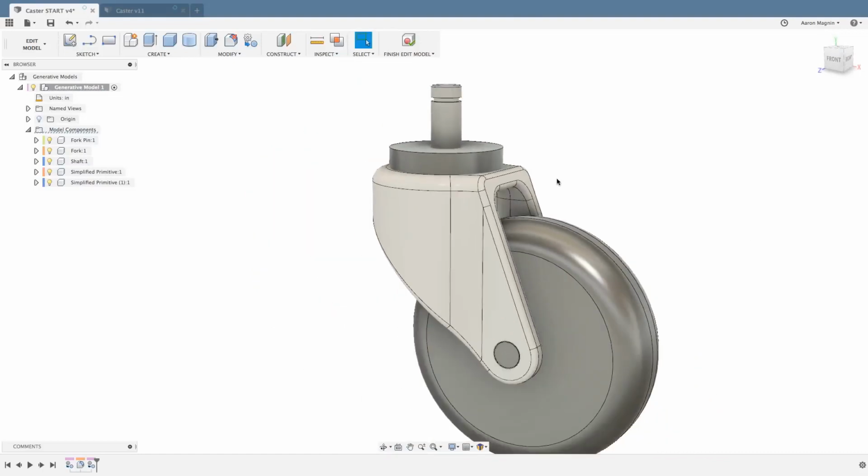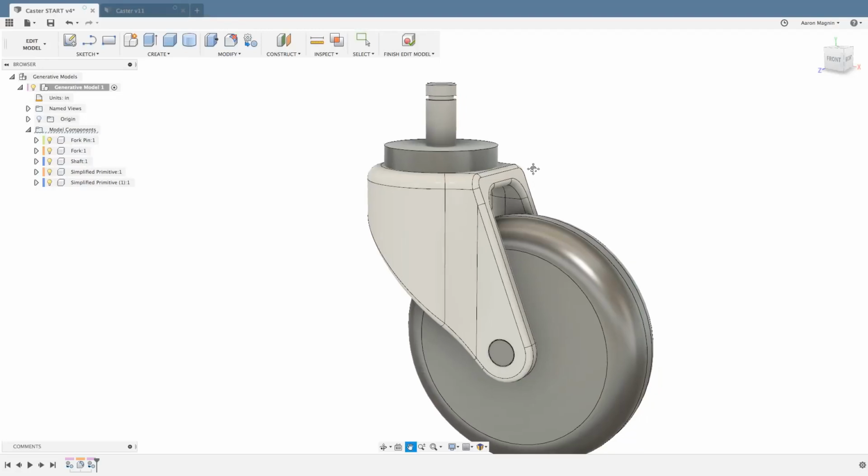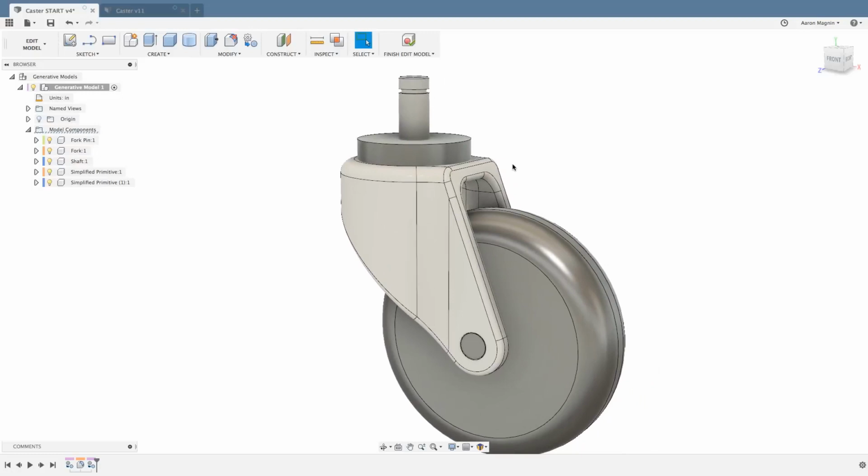So just like that, we've replaced two very complex parts, and now we're moving along and setting up these obstacles and preserves. And I should mention that, like the Simplify workspace in simulation, this edit model area within generative design is independent of the original design. So we can do a lot of design exploration here without worrying about affecting the original design. So some nice stuff there.